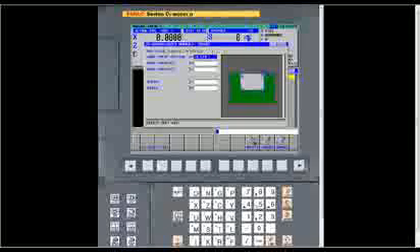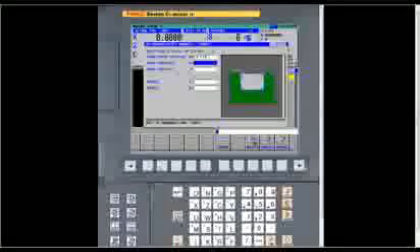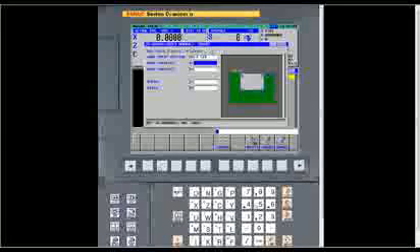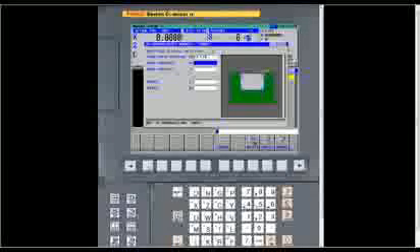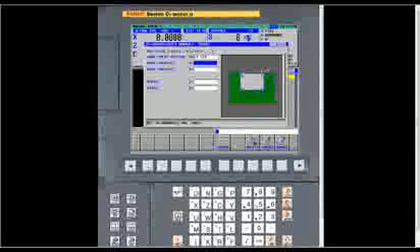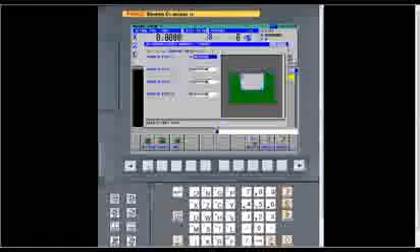And what's good about it is, here, it's asking you where you're defining the geometry of your groove, either Z minus or Z plus. So it just depends on how your print is toleranced, whether it's giving a dimension to the front of it. So it makes it very powerful. A lot of them, they always go to the back of the groove. With this, you can go either way.